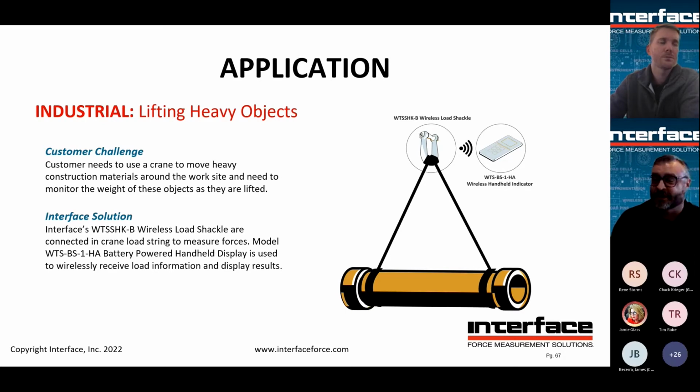And the reason for that could be if it gets hung up, or say it's strapped down and somebody forgets to remove the straps, or whatever. If you're lifting something, there should be a profile of the forces as that part is lifted and moved. And if they go out of range, you can stop, analyze, review, and make sure nothing's going to be damaged. Very important when moving a satellite or something that's very valuable, one-off. Very important to monitor all stages of the process as you're moving something like that.